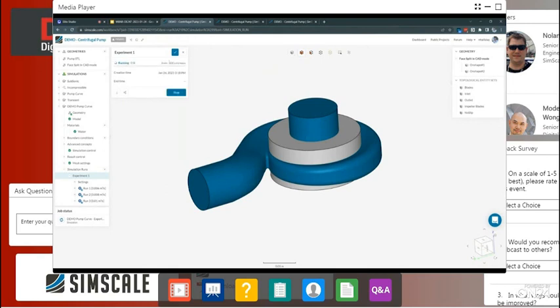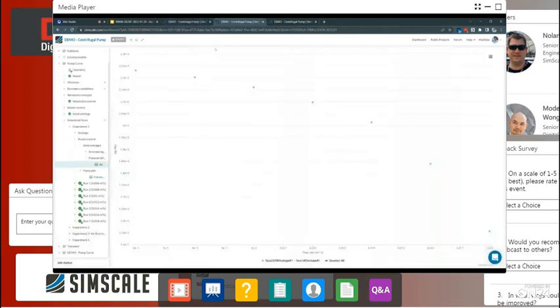the simulation is completed. Once completed, here's the kind of information we can extract. Here's a run that I did earlier, and I did a few more conditions just to get a little more data points. And this is just one such plot we can get. This is going to be our head rise versus flow rate. So for each of those individual cases, again, in about 10 minutes.